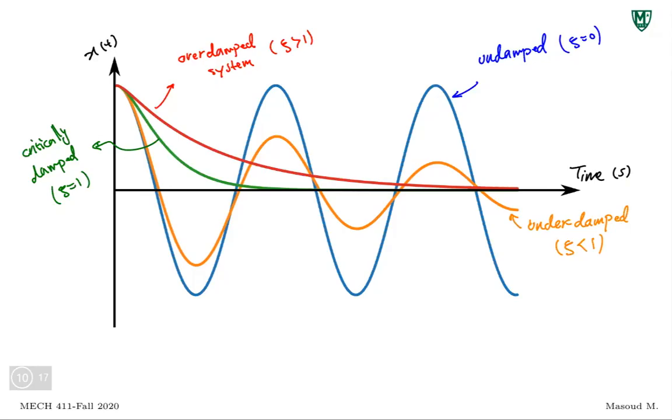However, the problem is it's very hard to design a system that is critically damped, because that value of C that you put there is just a constant, a damper, like a dash pot. Dash pot is another name for viscous damper. Sometimes you'll see that. Well, it's a fixed number, but system characteristics change a little bit. Mass, stiffness might change over using the system. So that C is not going to stay exactly equal to C critical.